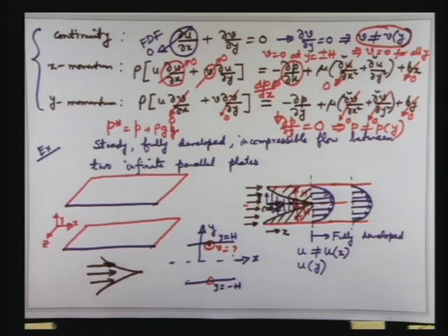Now I have already said that to simplify the matter, we will consider there is no body force, just to get the concept. To get the concept, bringing in piezometric pressure is not necessary. Okay, we can always complicate it. I can make it more complicated by saying that the channel is inclined, or the channel is vertical, or something like that. Let us not bring all those into account, because then we will just replace P with P star, but there is no new physics that is discovered. So always remember this, to illustrate a principle we should keep the situation as simple as possible, so that the principle can be illustrated in a better way.